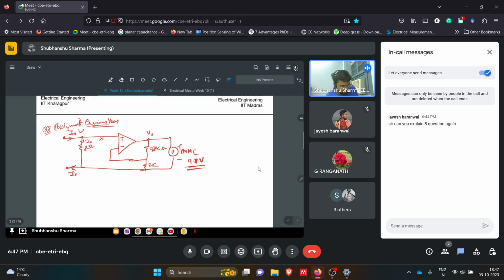So we can say what is the voltage drop across this branch. It is I in into 8, or 8 I in, if we are taking this as reference, as ground. So this whole branch will be ground. If we are taking that as 0 volts, then obviously all the drop is across this point. Now, since we have a negative feedback system, this 8 I in voltage is being transferred here due to virtual short. 8 I in. So it came here.